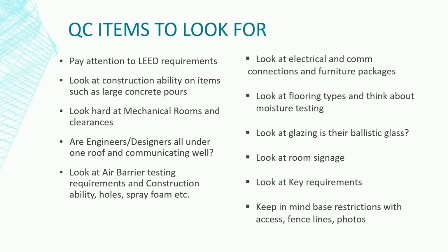Looking at constructionability on items such as large concrete pours. A lot of times what looks good on paper is just really not easy in the field. And a lot of times large concrete pours don't have access, and you need to look at how can we get broken up? How can we do the pours? Where can we get the trucks access? Where are we pulling water from? Those are things you want to look at.